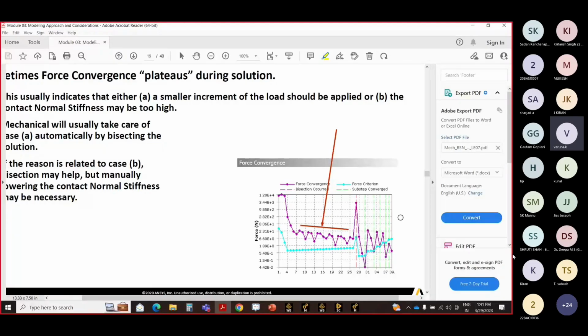There is no residual. But when you go for the nonlinear analysis, there will be residuals, which means the stiffness at each step will be changing. You have to evaluate that stiffness. You have to check what the stiffness is at this stage.